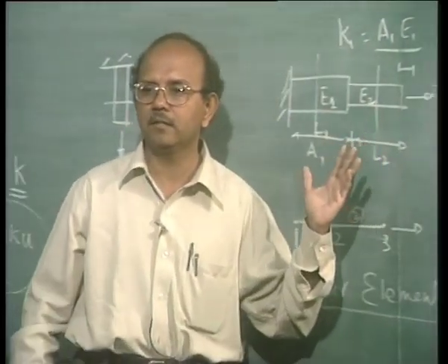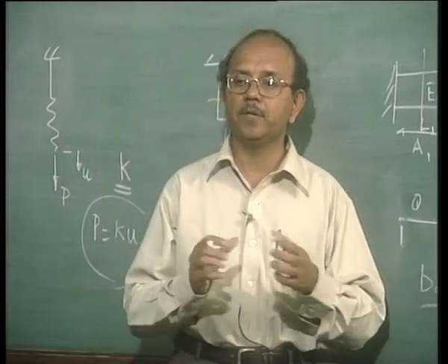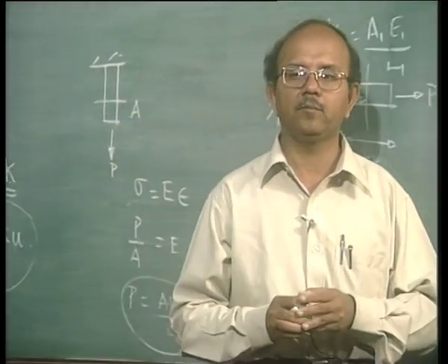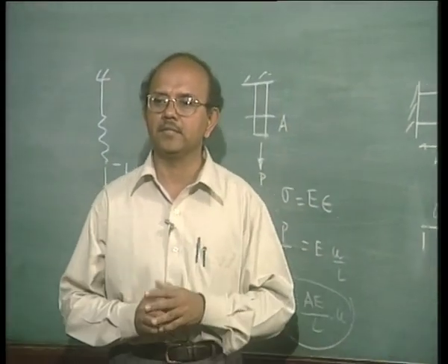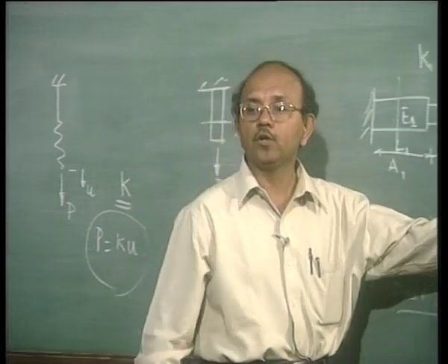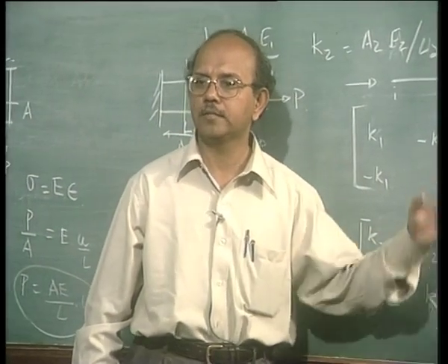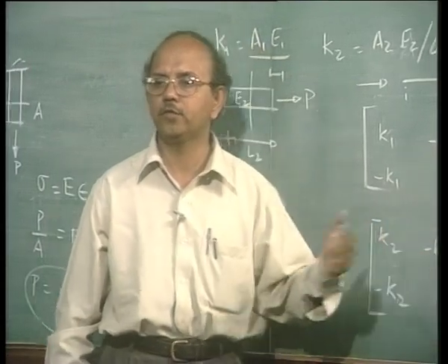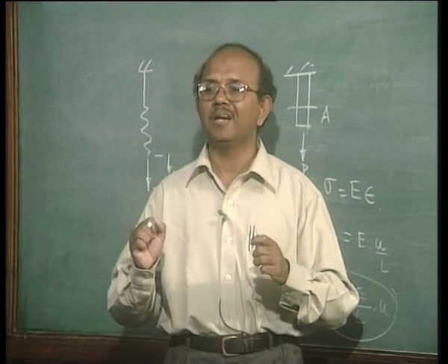We discretized it in terms of what we called elements. In this case, the behavior is bar. We will come to what is behavior in a minute, but in this case, we call this a bar element, so we discretized it. The next step is we wrote down the stiffnesses of individual elements. The third step is I have to assemble them.